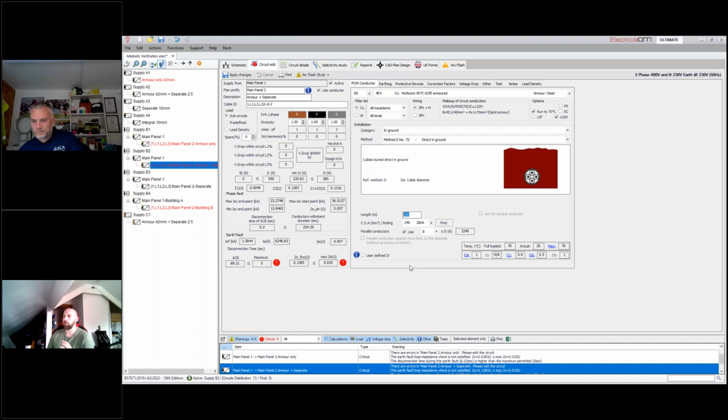Inland not too bad, but if you're closer to the coast you're going to have a lot higher water tables, so you know, drainage and everything, you don't want to blow the armoreds. So you might end up having to put in armoreds with additional waterproof protection, as a layer within the XLPE and everything else as well. So again, I'm running off these, but yeah,